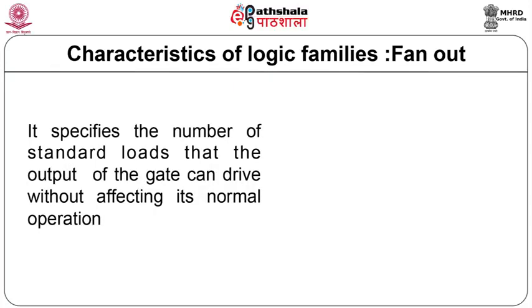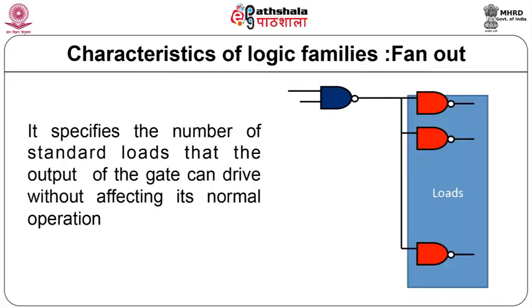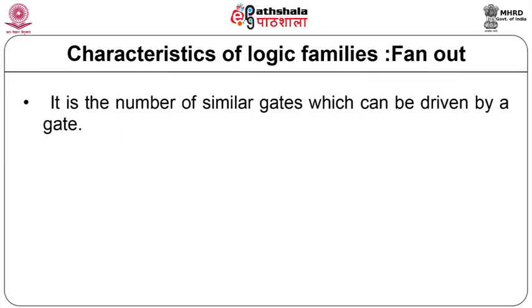Next characteristic of logic family is fan-out. It specifies the number of standard gates or loads that the output of the gate can drive without affecting its normal operation. It is the number of similar gates which can be driven by a gate.